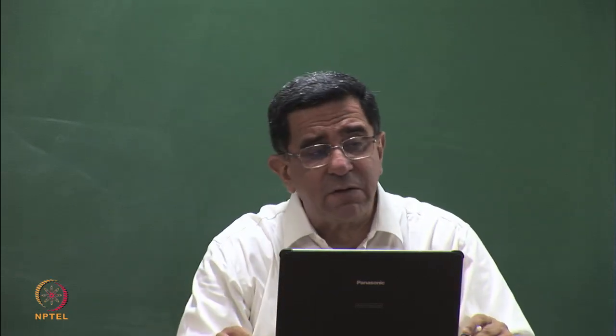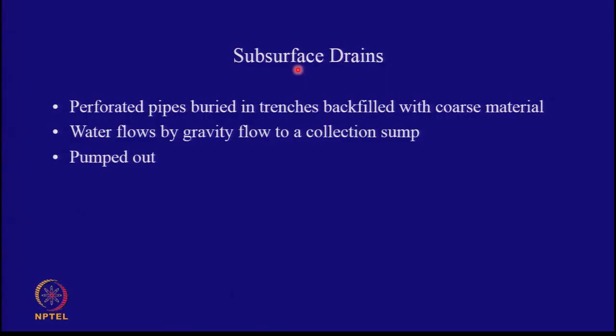You might want to put a subsurface drain in conjunction with this. A subsurface drain is something in which perforated pipes are buried in trenches and backfilled with coarse material. Water flows by gravity to the collection sump and is pumped out.